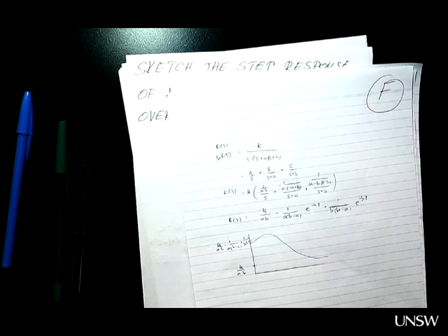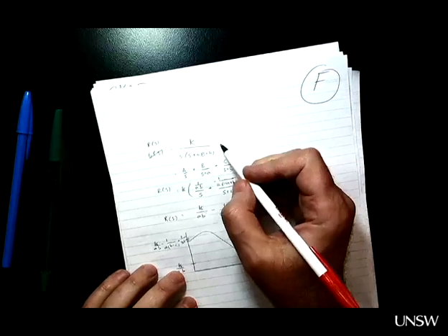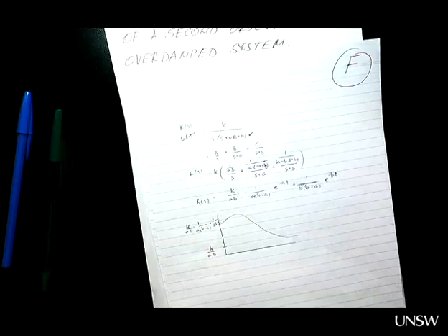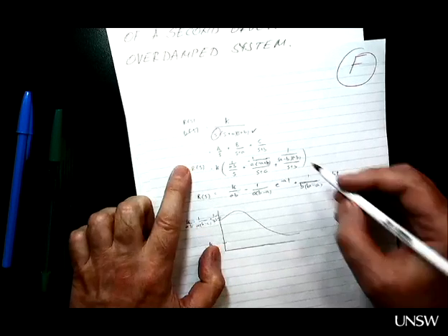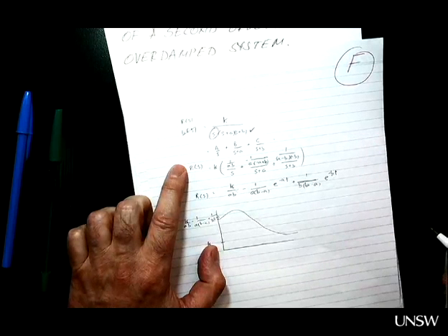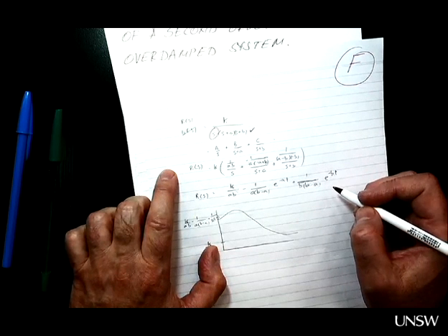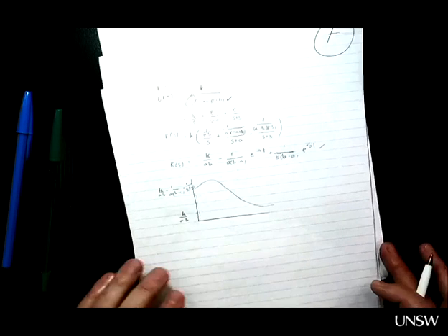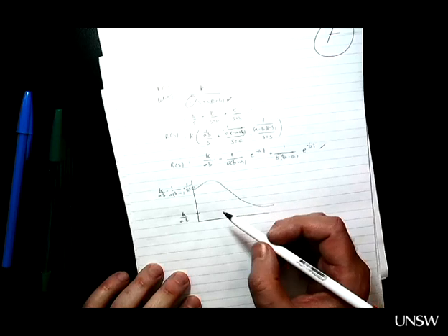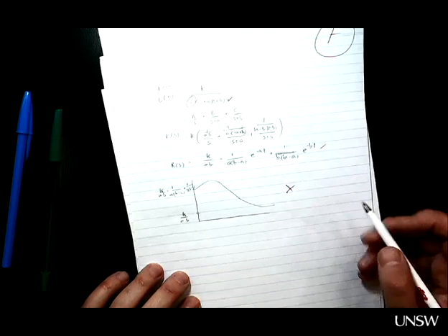Don't worry. Okay, so this is the front group. Overdamped system. Did we say overdamped? Yes, overdamped. So this is okay. Overdamped system has two real and different poles and step input. So this is correct. Okay, now they're trying to do partial fractions, although this case exists in the tables. So it is a bit of waste of time, nothing wrong so far. Okay, this looks right. I can't check every single coefficient here. This looks right, but this doesn't really look right. The actual question is sketch, so the sketch is not that good. Possibly, well, it looks exponential, which is probably the only good thing about this graph.